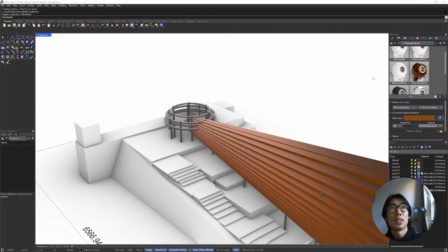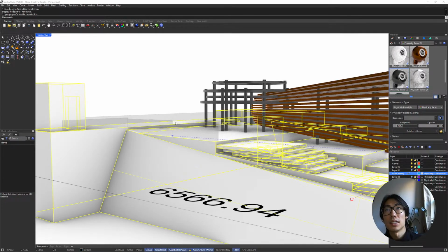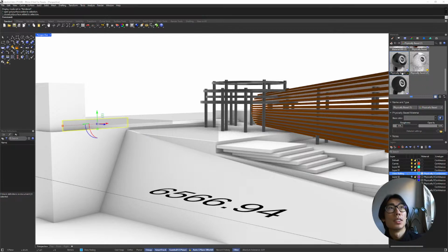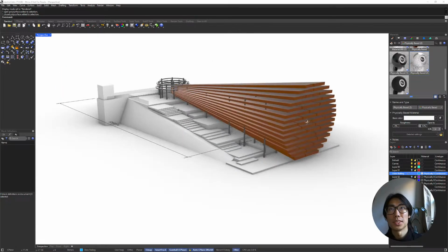And then we have this kind of dark metal. It's already been applied to this unit here. We'll go ahead and apply that. Let's say, oh, we can turn on some other layers here. Always good to name your layers. We'll call this one glass. Right. So this, we've taken a sort of glassy material. So we turned the roughness all the way down. Roughness 0 makes it shiny. Then we turned opacity down as well to make it simulate glass. So here we have our beautiful design.